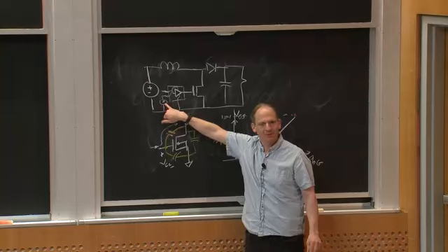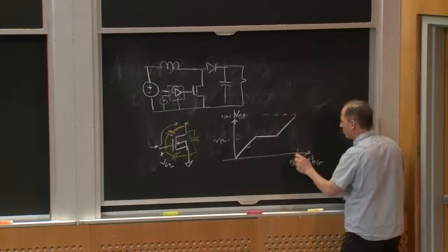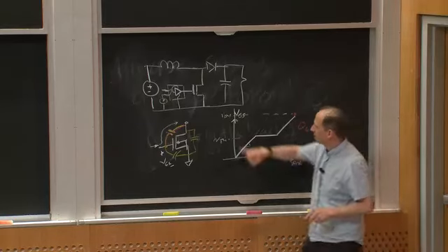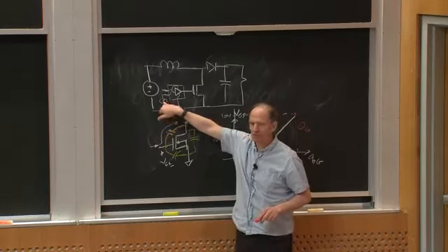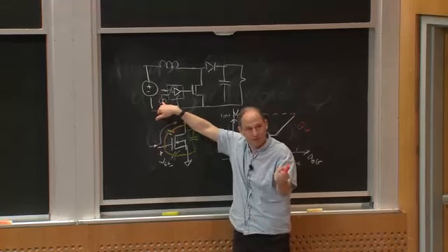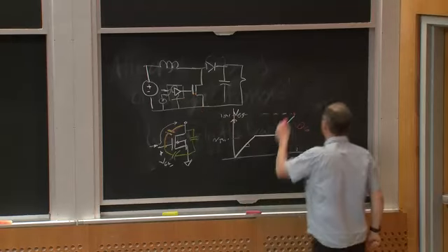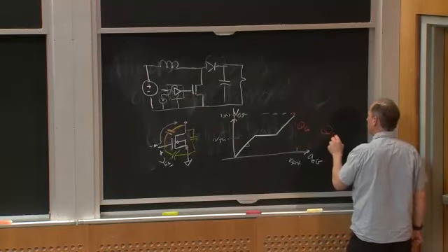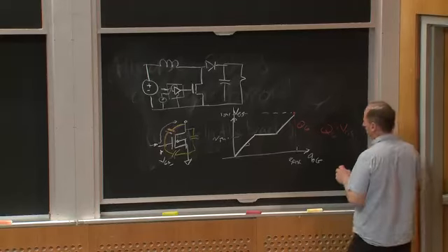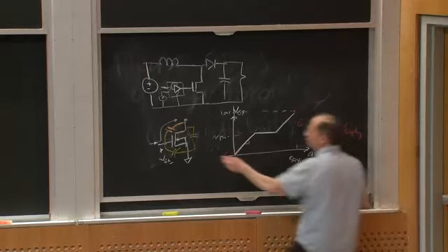Well, we talked about this when we talked about switch capacitor converters. If I'm supplying some value Q sub G total, that supply is always coming from the gate drive power supply voltage, 10 volts or something. So the amount of energy that comes in to charge up this gate is going to be equal to QG times VGS max, or V supply, where this is my gate drive power supply.